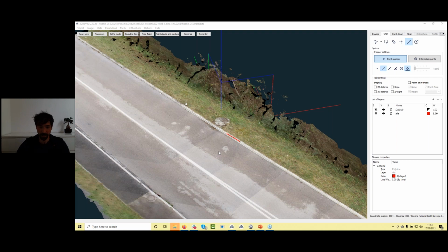GCP points per kilometer, but I would warmly advise you to invest a bit more, and buy the Phantom 4 Pro, because there was a change in the camera. Phantom 4 Pro has already a 1-inch sensor, 20 megapixel camera, and what's more important, it has a global shutter. You can Google it on our website, what's the difference between global and rolling shutter. If you like to get accurate results and not use too much ground control points, definitely we would advise you to go with the Phantom 4 Pro. So not with the standard Phantom 4, Phantom 4 Pro.